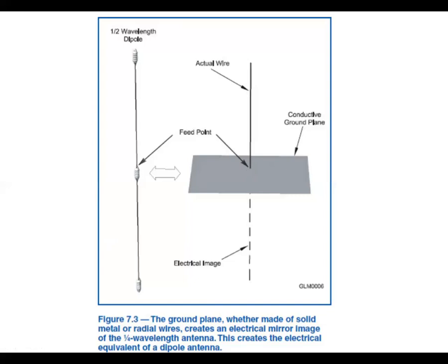And then there's, I forget what, I'm drawing a blank. Counterpoise. You can use a counterpoise, which is just a long length of wire that's running along the ground that isn't adding to the radiation of the antenna, but it does provide the second half of the antenna for it to balance the current flows. So when you're looking at a vertical antenna, just think of it as half of a dipole.